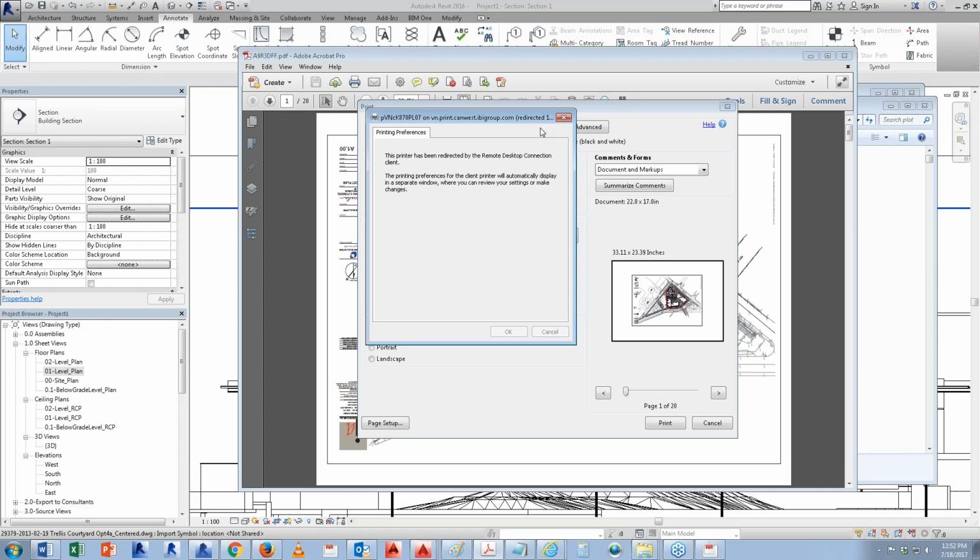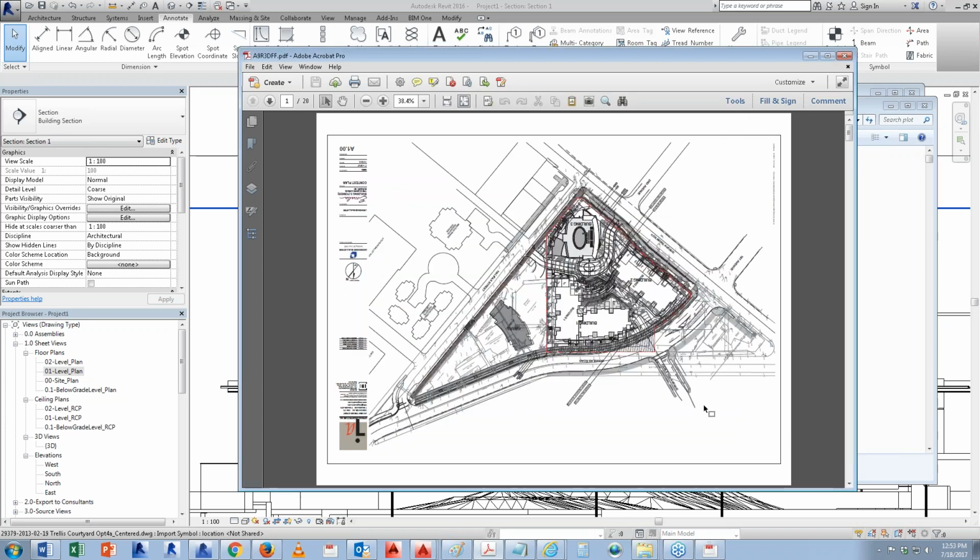If you don't put it in, some of your drawing looks muddy, okay? Because I do have people complaining. I'll just say, did you set this? Unfortunately, the default is always default. It just doesn't do much. I try to change it in the printer settings, it just doesn't do much. So what I change is the page size and the quality, automatically on the photo. We change it to CAD, yes. And then the pen setting, always choose line quality, okay? Because the line will make it very fine, very nice. All right, those are basically those settings.